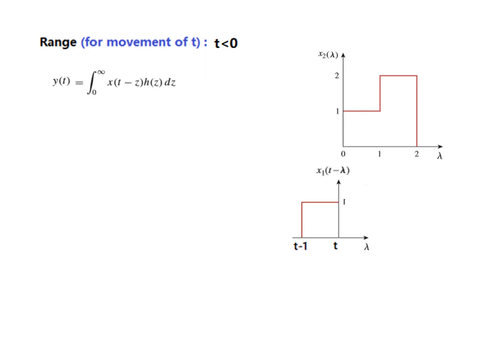And what actions did happen? Okay, we'll be using this integral formula throughout. This shows the overlap between the two signals, and since there is no overlap, this term will be 0, and so our output will be 0 for t less than 0.